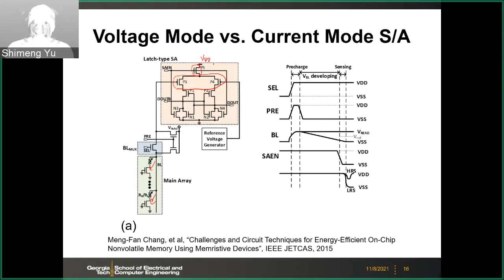So this is a PMOS version of the differential pair. And then the load to the PMOS is this NMOS region. And as we discussed earlier, if you want to flip fast, you can use a latch here as a load. These 4 transistors are a latch. This is like a load to flip.